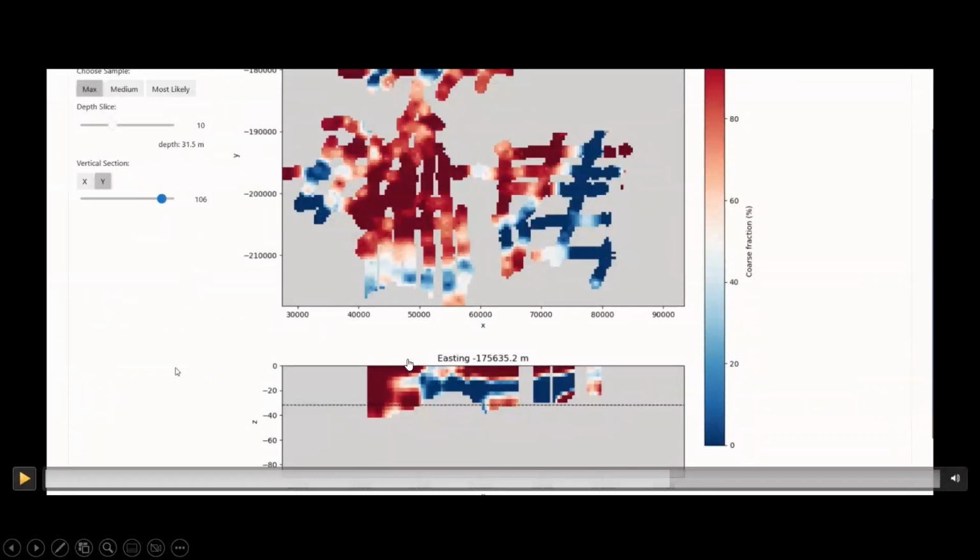If you want to decide where you want to recharge, this might be a great location, because what I'm showing is the water table. So I'm just ignoring all the cells below the water table. And so there's a direct pathway. But this may not be a great location because it'll be blocked by this clay. So this is the simple first-order check that you can do by visualizing this 3D model.